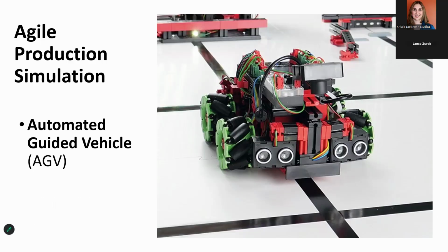The six-axis robot located at the DPS station then places the workpiece on the automated guided vehicle, or AGV as we'll sometimes refer to it, for transport to its next destination or station. I should mention that the DPS station also contains the central control unit, which is a Raspberry Pi, and the environmental sensor, which helps to measure the different environmental conditions in the factory. This is going to be things like the lighting and the temperature and air quality and what have you.